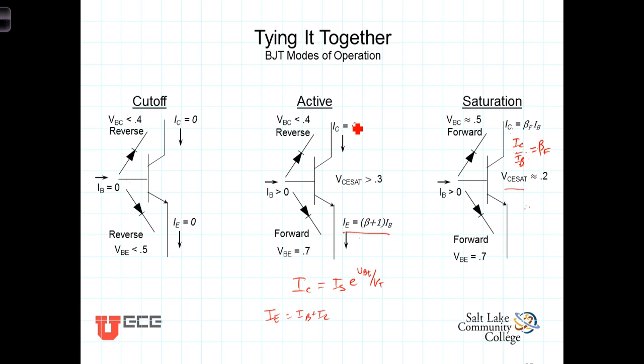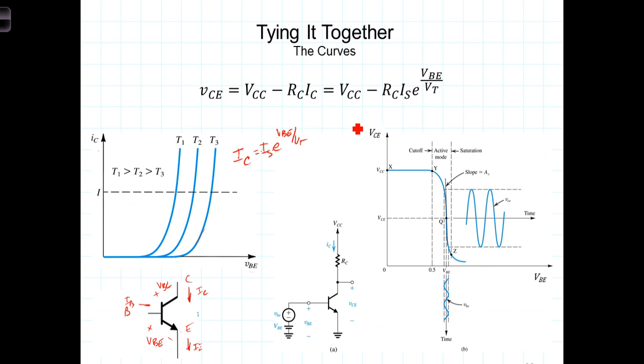So that describes the relationships between currents and voltages within the transistor itself. And we have seen that we can place a transistor into a circuit. We can connect to these terminals voltage sources and resistors that influence the terminal voltages. By doing so, we say that we bias the transistor into the active region, where there is a relatively linear relationship between voltages at the input and the output.